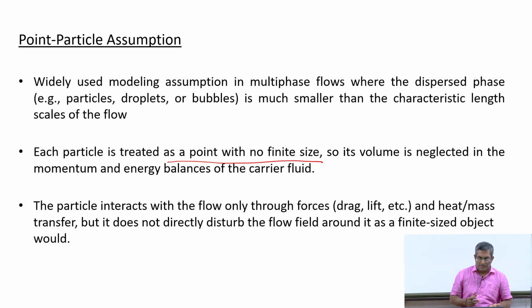So what does that mean? That means that, let's say you have a particle here, and it is moving in the flow, then it can create its own vortices, and you can also have vortex shedding phenomena. But if you assume that such phenomena are absent, then you can consider only the drag force on the particle, for example.